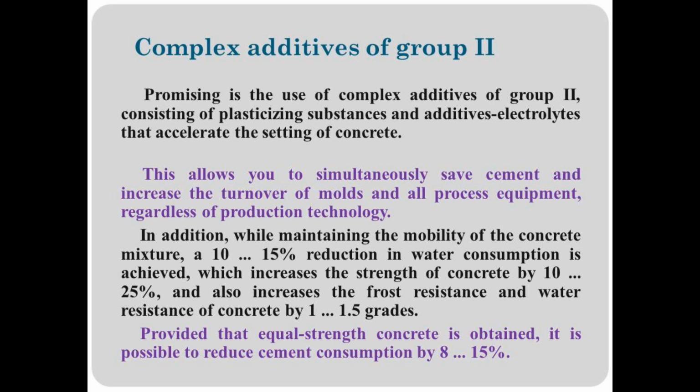In addition, while maintaining the mobility of the concrete mixture, a 15% reduction in water consumption is achieved, which increases the strength of concrete by 25%, and also increases the frost resistance and water resistance of concrete by 1.5 grades.